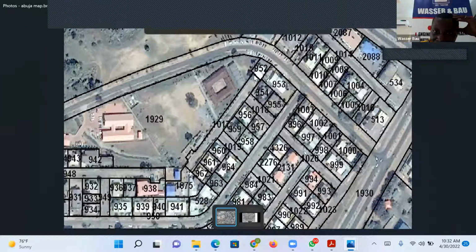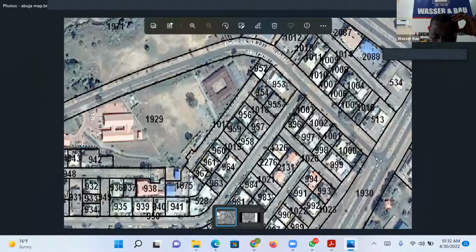So what you do, you can see that if I know the elevation, the spot height, I can know that if water from this catchment is flowing towards this drain, and then if this one is flowing towards this drain, or this one is flowing towards this drain, then once I know that, I can know which one will empty where. So I can know whether this one is flowing down here, or whether this one is flowing down here. Okay, based on the elevation and the spot height.